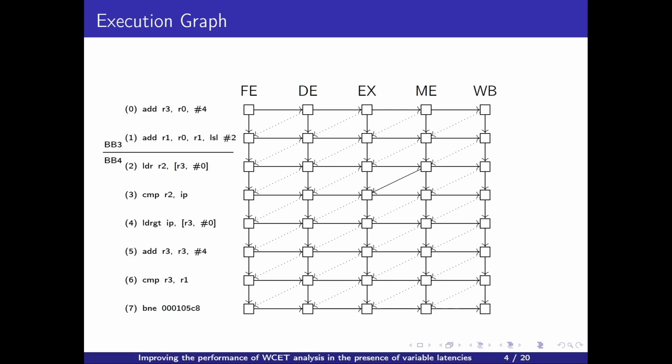The dotted edges indicate that one node cannot start before the start of its predecessor. For example, the stage fetch of instruction 1 cannot start before the start of stage decode of instruction 0, which frees the queue between fetch stage and decode stage that allows instruction 1 to enter the fetch stage of the pipeline. This type of edge represents the concurrent use of a resource, in this case the queue of size 1 between fetch and decode stage.